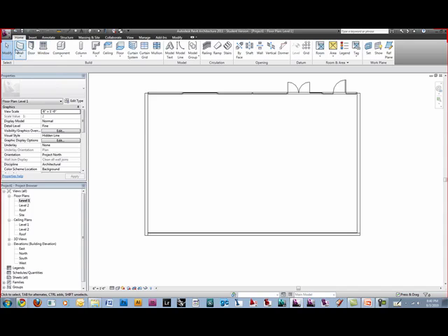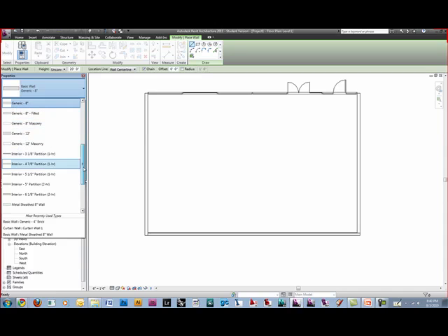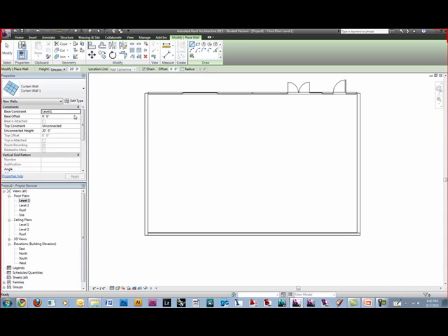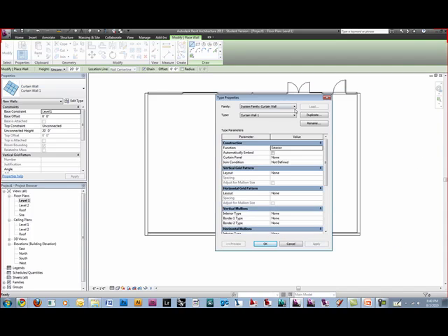So what we can do here is, if I go to my walls and I choose down here, let's just go to a curtain wall, which is blank glass. And if I go to the properties of that wall, I go to my edit type. Oh, there it is. And I scroll down, you'll see an option right here for automatically embed. And what that does is, if you draw this wall on top of another one, instead of placing 2 walls, it'll actually just embed the one you just drew inside of the other wall. So let me do it without doing that, and then I'll show you with that.